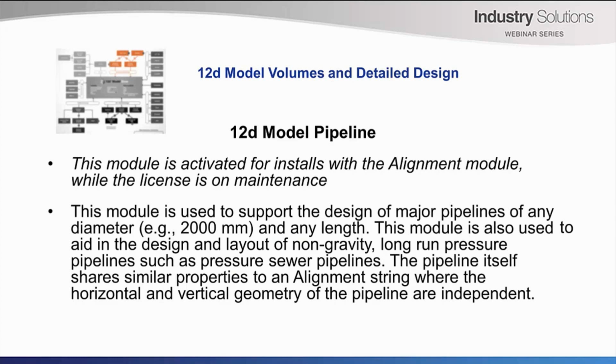The pipeline itself shares similar properties to an alignment string, where the horizontal and vertical geometry of the pipeline are independent. These days, most people tend to use the superalignment, as the superalignment now can have a diameter or a width and a height.